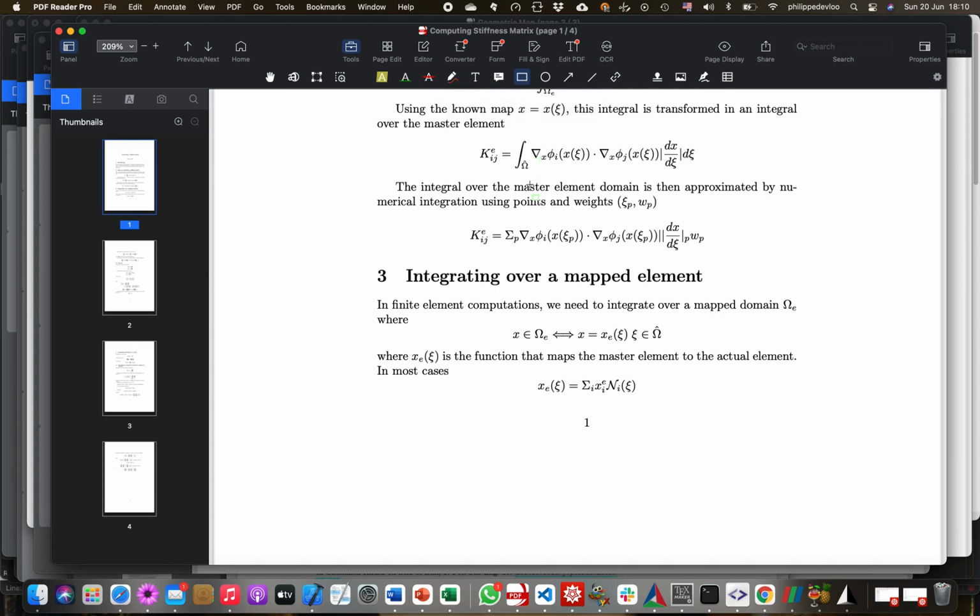Well, we've seen in the previous video that this part is computed using the contribute method of the mat statement. So the element stiffness computation, which we're going to document, is basically going to set up the values of the material data structure, compute the contributes of the mat statement, and sum the contribution over all integration points. Okay.